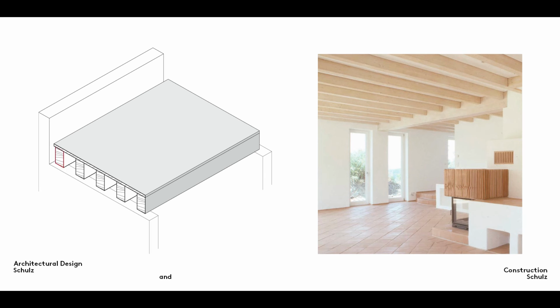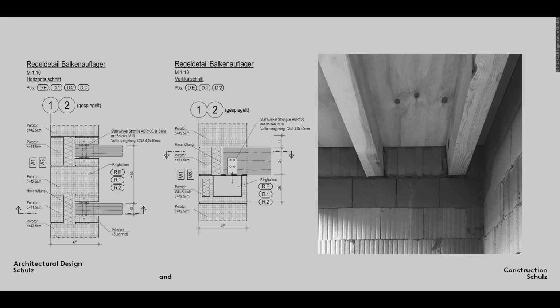The first joist is placed a short distance from the rising wall to compensate for tolerances and to allow the wall to be finished. The distance between two of these parallel edge joists should be divided equally to give a reasonable centre-to-centre spacing for the remaining joists. The boards or wood composite sheeting laid on the beams then project slightly to fit flush with the wall. This photograph taken in Felix Haustein's house shows how the edge joists are placed in relation to the rising walls. The photograph and the accompanying drawings also explain how a wooden beam is supported on a wall.